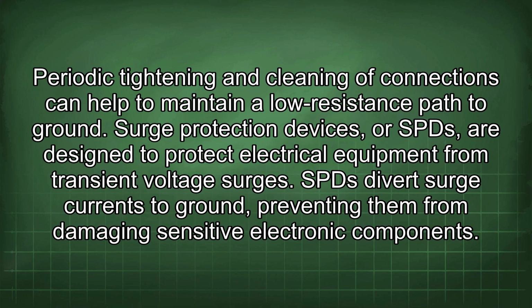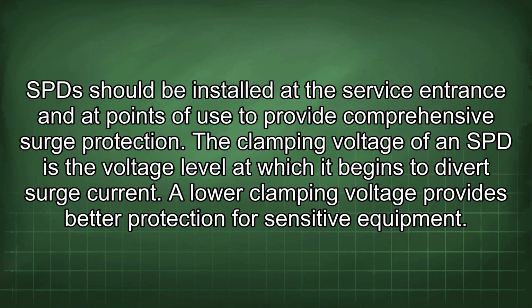Surge protection devices, or SPDs, are designed to protect electrical equipment from transient voltage surges. SPDs divert surge currents to ground, preventing them from damaging sensitive electronic components. SPDs should be installed at the service entrance and at points of use to provide comprehensive surge protection.